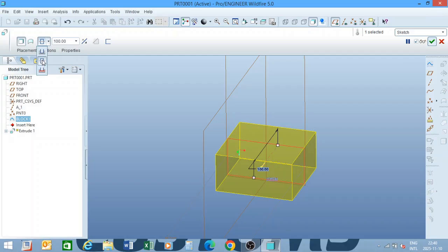I like to use the symmetrical one because, like I've said before, it keeps the drawing symmetrical. And if you do other functions where you're using the datum planes to mirror or copy or pattern or anything in that line, it makes it a little bit easier. Symmetrical is always better, then you don't have to calculate offsets and so on. So I use symmetrical.